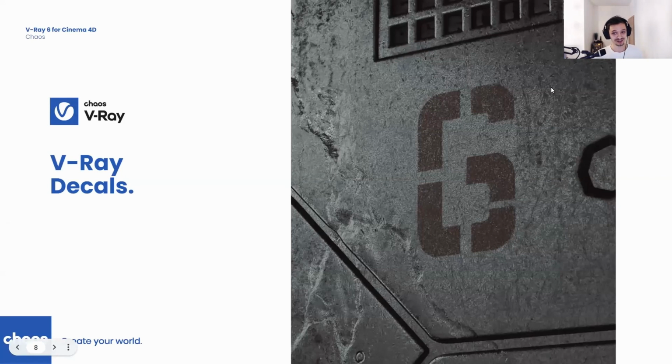Next up, we have V-Ray decals. Now, this is another awesome one because it makes creating decals a lot easier. You don't have to worry about UV mapping anymore. You don't have to worry about selection tags anymore. You just create a V-Ray decal object, you apply a material to it, and then you just position that object so that it points at the object where you want to project that decal. That's kind of it. Again, no UVW unwrapping or such.